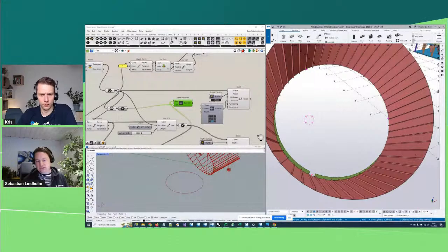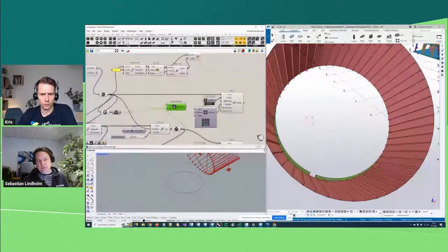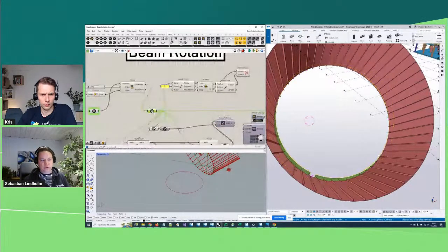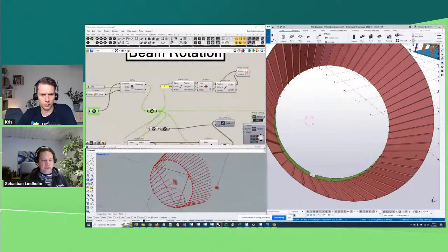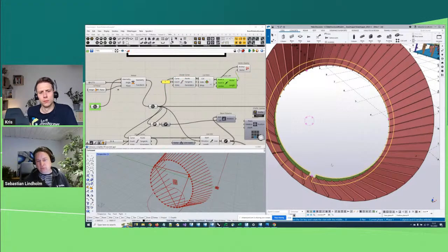So it would be from the start of the circle here to the first control point, and that's the axis we need to find. And because we can't get this beam back into Grasshopper, because that would be a circular reference, we need to instead work with this input circle and just divide it using 3 points. That way we can recreate this output that we get in Tekla with 3 points.